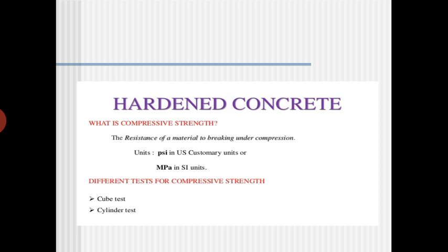In case of this shear strength, when you are conducting the shear strength analysis, it is not about the tensile stresses, and it is not about the compressive stresses. So normally we are going to conduct this by applying equal forces which are in opposite direction. It is not like tensile and compressive stresses, but we will apply stresses on the hardened concrete which are of equal force or equal stress, opposite in direction. Maybe in detail in the IS code it is there. We can find it out. Maybe I'll give you some references at the end.